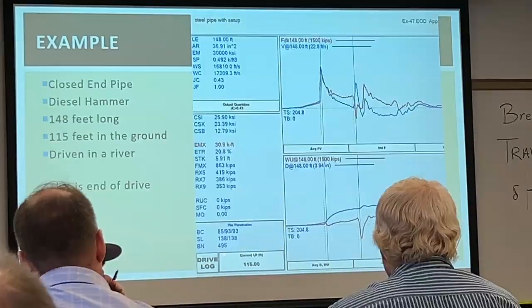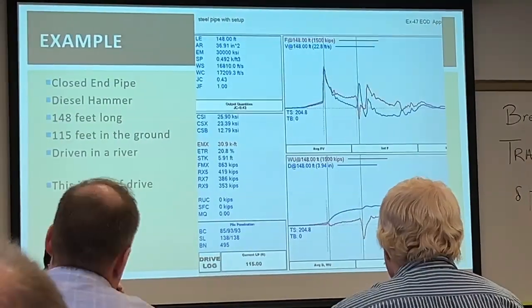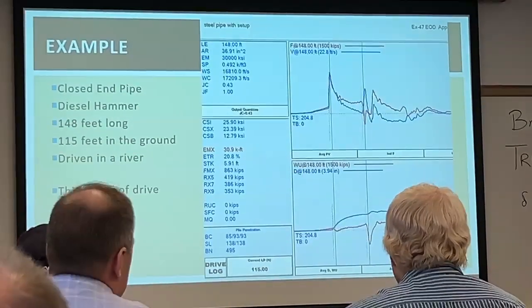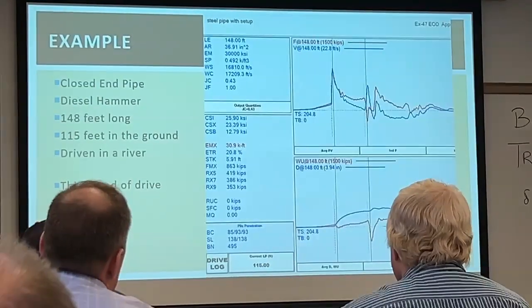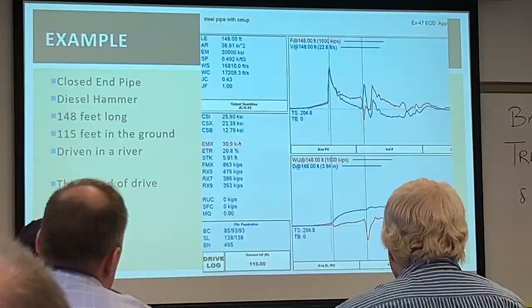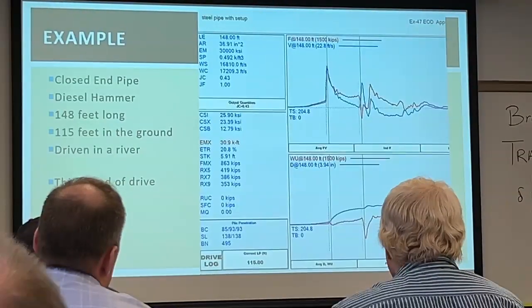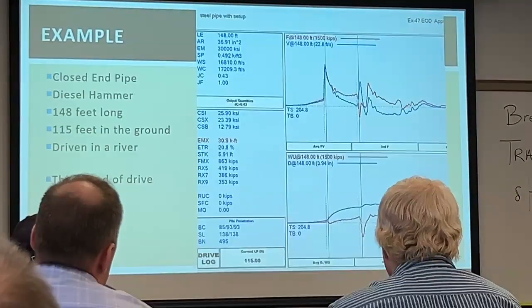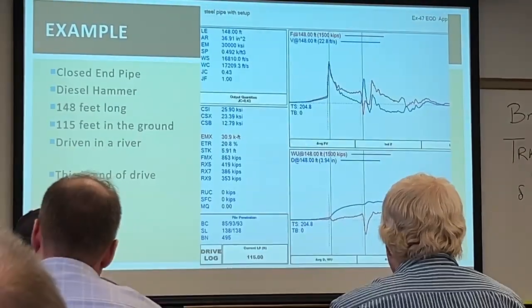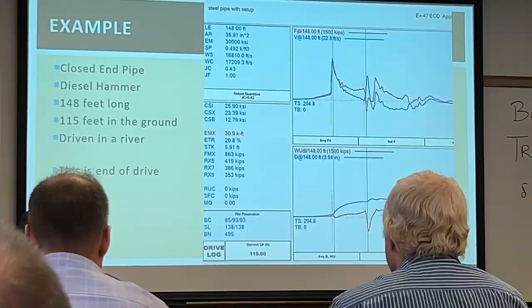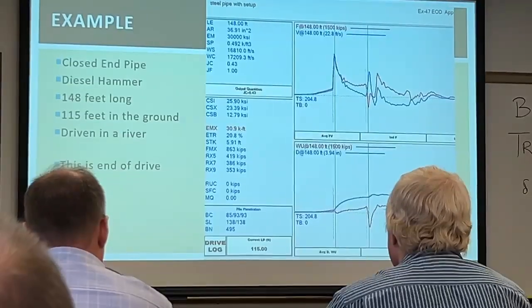what we might see is that there's higher indications of shaft resistance. And those higher indications of shaft resistance, we can then add to the end of drive end bearing, because we're able to mobilize things up high more easily on the restrike, and we will be under mobilizing what's happening in the rock down at the bottom.